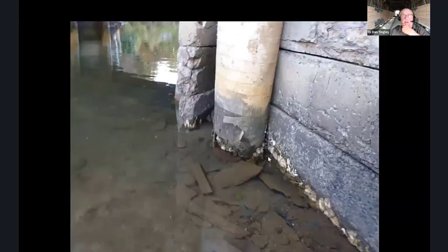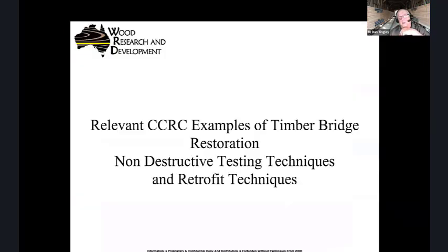People put Denso cloth, never do this. This just leaves a chance for more decay. Moisture content runs up higher in the piece, and the marine borers didn't get you, decay did. So there's better ways to do this that we'll talk about.